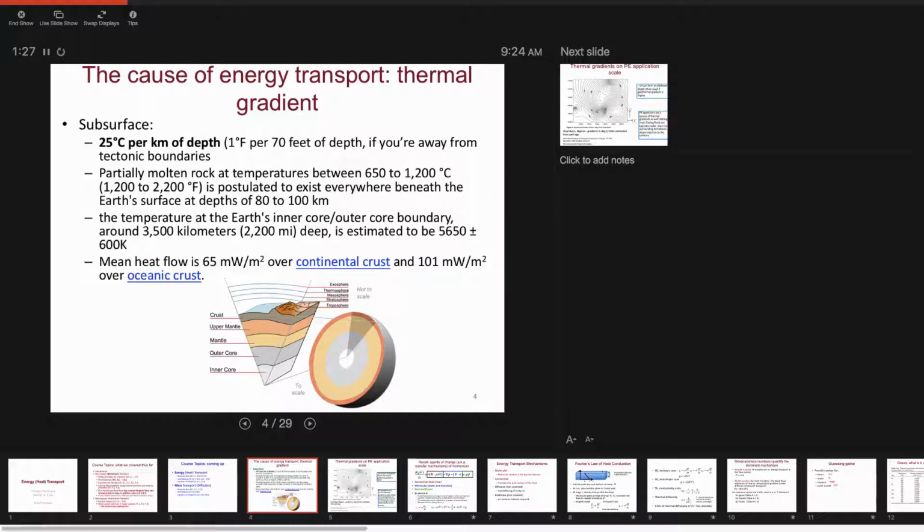Now, that said, the essential mechanisms, or why this transport actually happens, are very similar. They're ultimately molecular. Basically, we have temperatures related to the velocity, or average velocity, with which molecules move, especially if I have fluids. So they have some space to move around, and that's correlated with the velocity. And basically, just through molecular collisions, those higher velocities will get transferred from regions of higher temperatures to those where I have lower temperatures. So the essential origin of all of this is molecular, which is very similar to the treatment of momentum transfer.